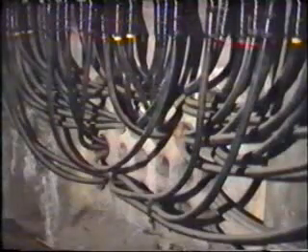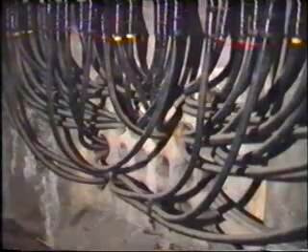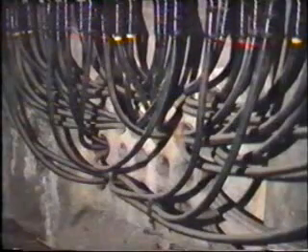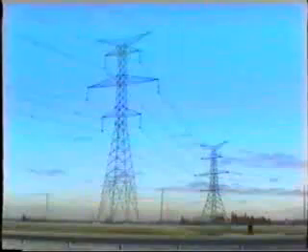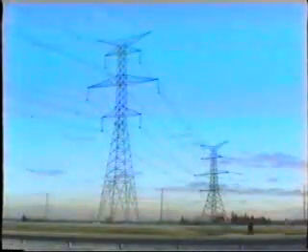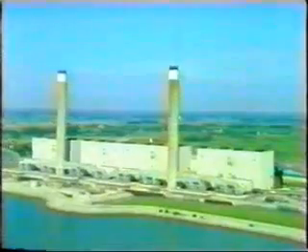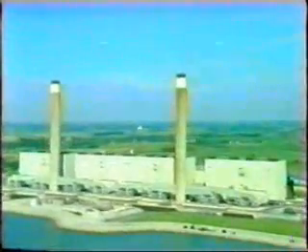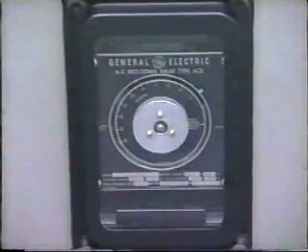Automatic reclosing is not usually employed on underground cable systems, as these are not susceptible to temporary faults. A fault on a cable system is usually due to a permanent fault in the cable itself. The type of reclosing scheme employed varies according to the function of the line itself. For example, is it a transmission line or a distribution line? Is it close or far away from a generating source? The reclosing relay generally allows for several attempts at reclosure with different time delay settings.